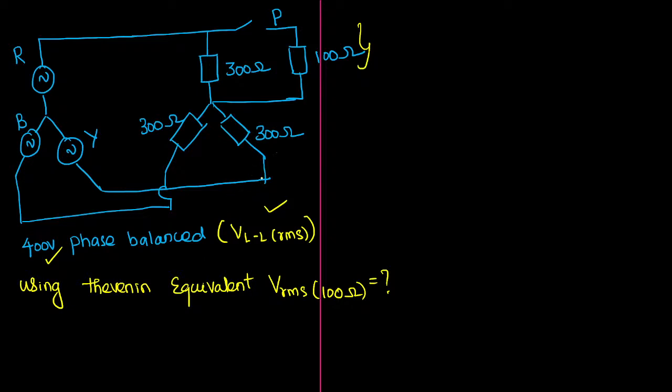If they are giving phase voltage, then that will be mentioned in the question itself. Otherwise, if they haven't specified the given voltage, then consider it as line to line RMS voltage. Okay, you may proceed now. Bring the answer.